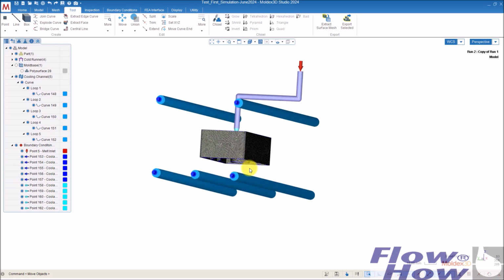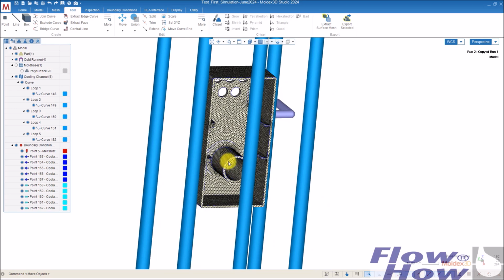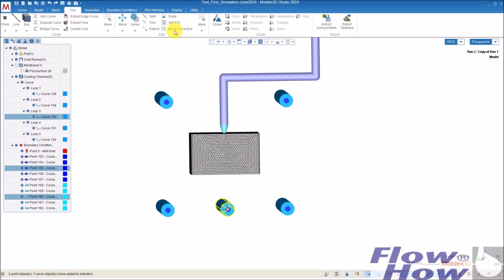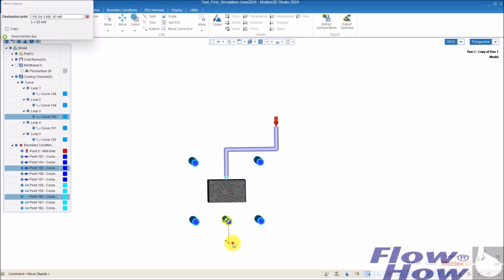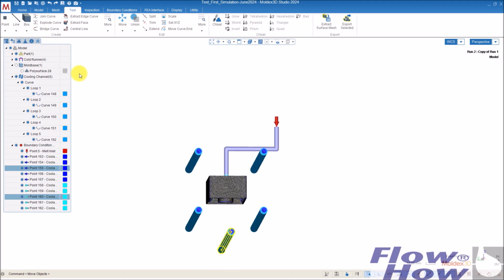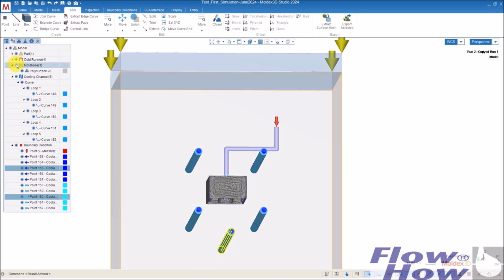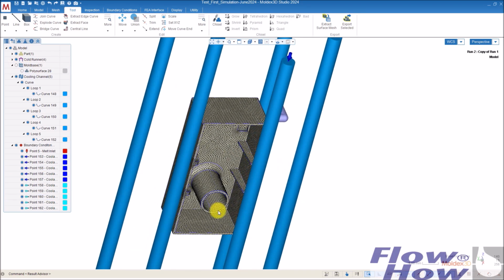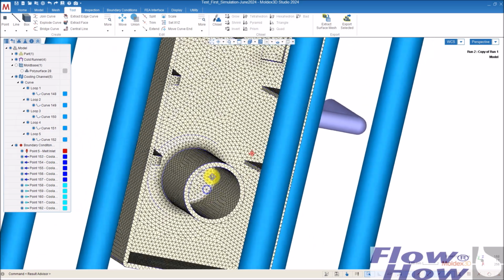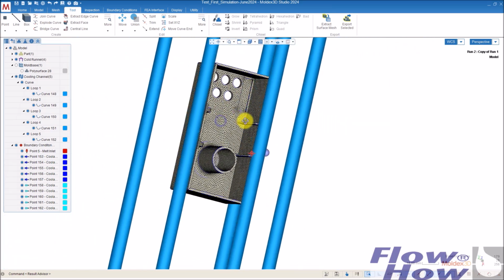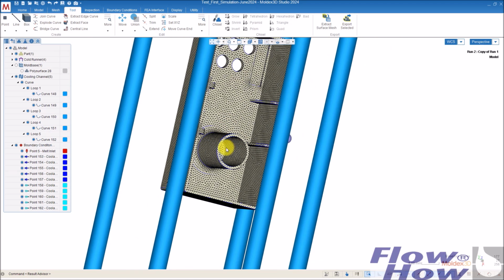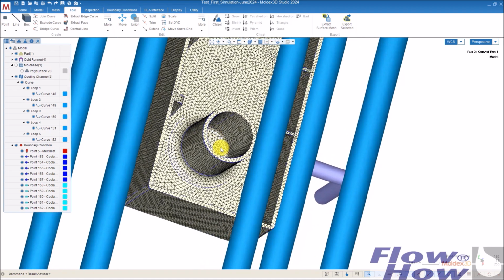I also want cooling up in that area here. So in this case, I'll just take this, move a bit downwards, of course not outside the mold base. I'll just check, yeah, it's not outside. And then I want baffle cooling up here, and yeah, just to take the heat out here. Maybe you could also do it here, but anyway, I'll just do it here.